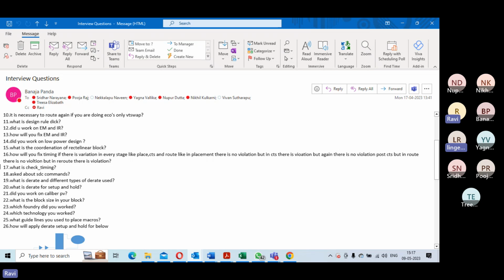So basically, this is not like it will happen initially. It can happen over a period of time, right? Due to constant bombarding of electrons, what can happen is the hot electron effect, the surface could actually peel off. So there could be a rupture in your net. The density of current flowing is more than what that net can handle, say for 10,000 hours, but constant bombarding can actually create this issue. So that's why it can rupture.